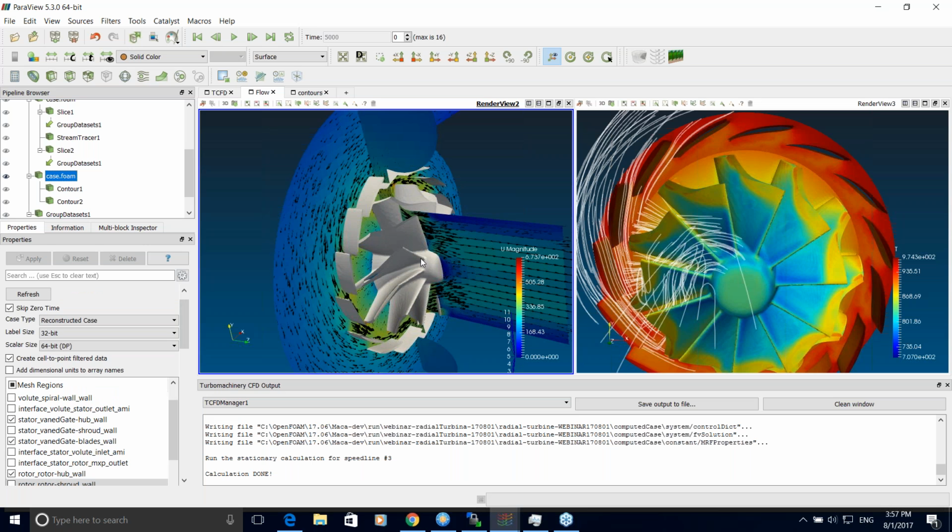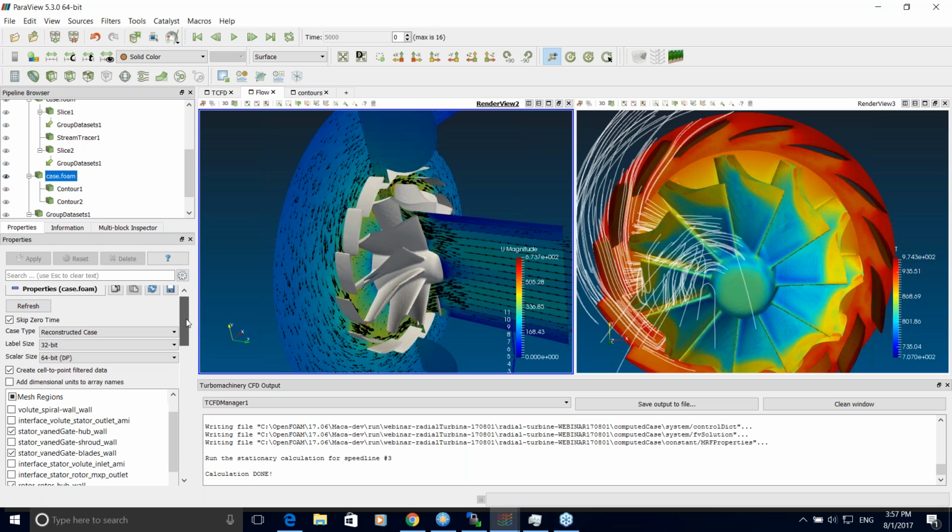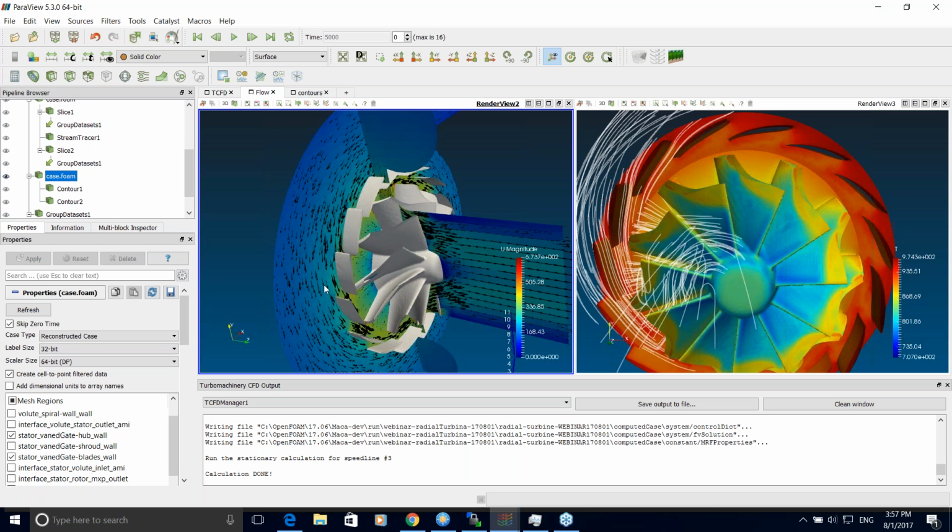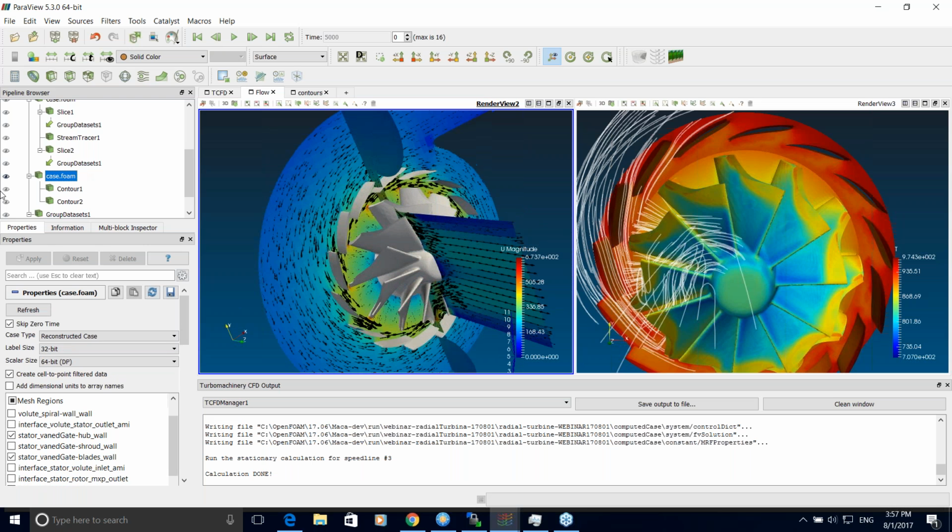It is just a mapping of the neighboring interfaces on each other, and there is no restriction. Only, of course, these interfaces must lie over each other. There must be only a line, but the meshes of these two interfaces do not have to be the same and have point-to-point correspondence.